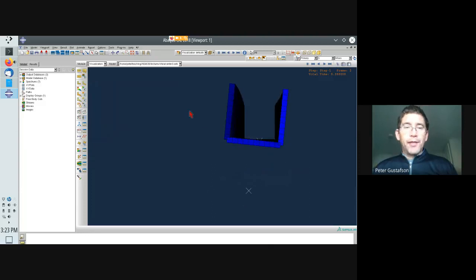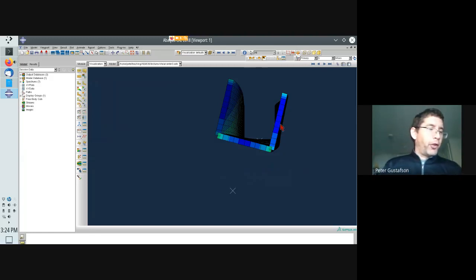So now I've applied this load way down at the bottom. You can see I've gone beyond what we know to be the shear center. Now you can see as this thing bends, it's still bending to the left, but now it's twisting clockwise. So you go far enough down and you're going to add a moment that causes it to rotate clockwise.